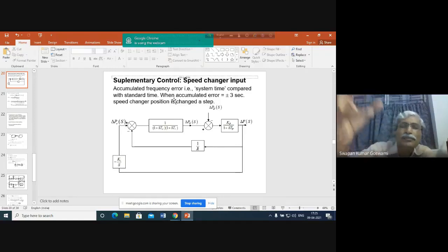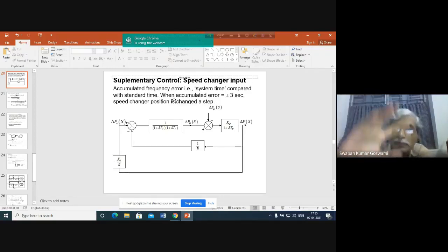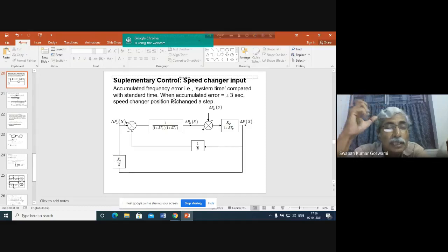Similarly, if you draw power from the system, this is undeclared power. You have not previously booked this amount of power and you are drawing power from the system. If you are drawing power when the system frequency is already low, then you have to pay a very heavy amount for drawing this power. The power price will be such that it is a penalizing price.